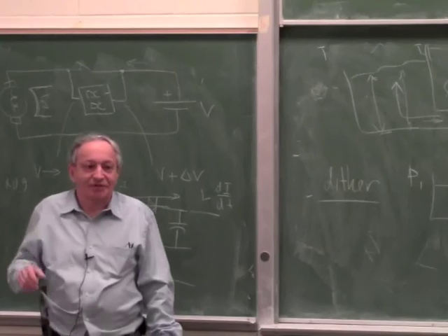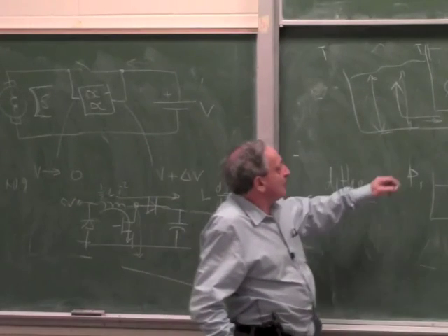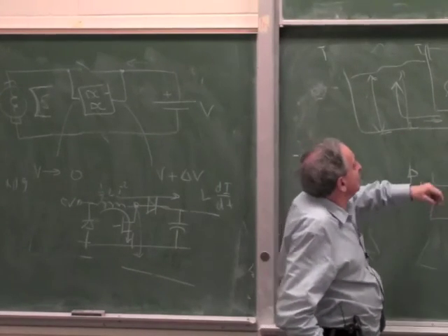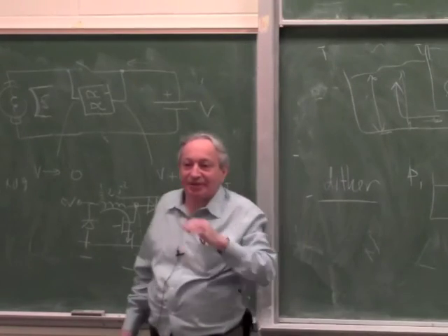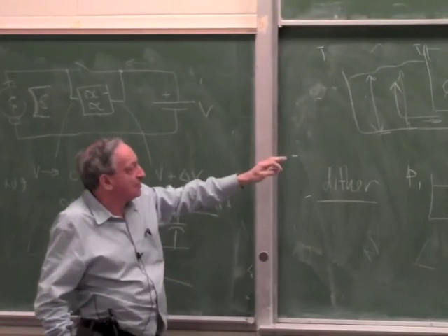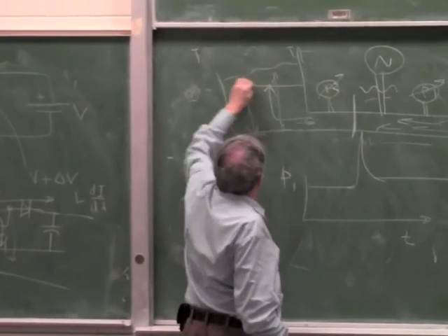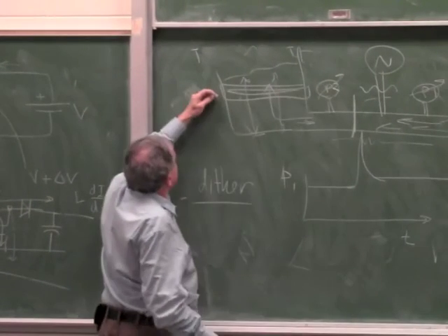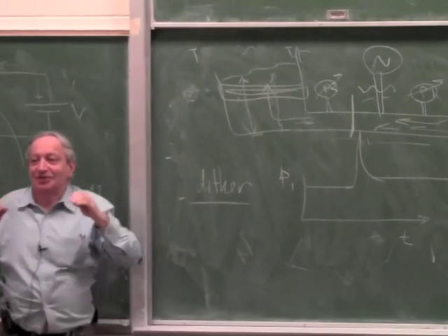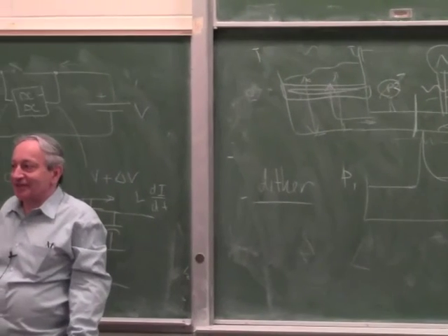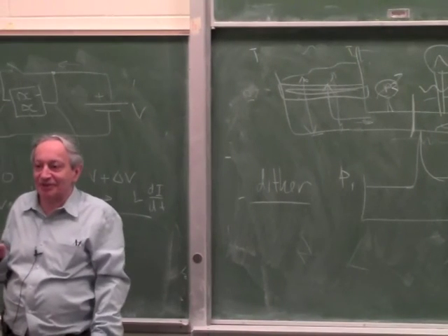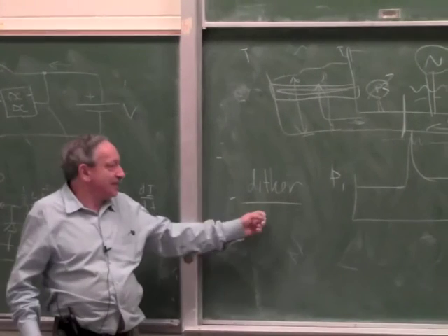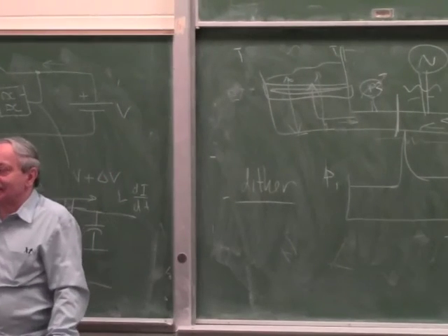dynamic friction. So the way you solve it, you put a small AC signal into the servo. So let's say you have a pump here, and that pump just gives you a pressure pulsation, or a sine wave, small variation in pressure. So what this means, that wherever you have some pistons in the system, these pistons are always vibrating, so they don't have static friction. Okay? And that's a very powerful technique. Without that, you cannot actually build a high-performance hydraulic servo. So that's called dither, and that is also used in electrical servos.